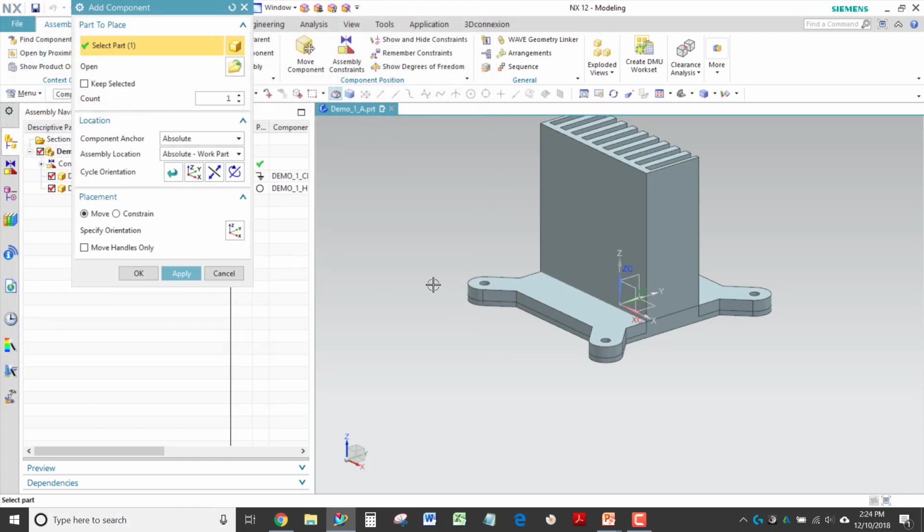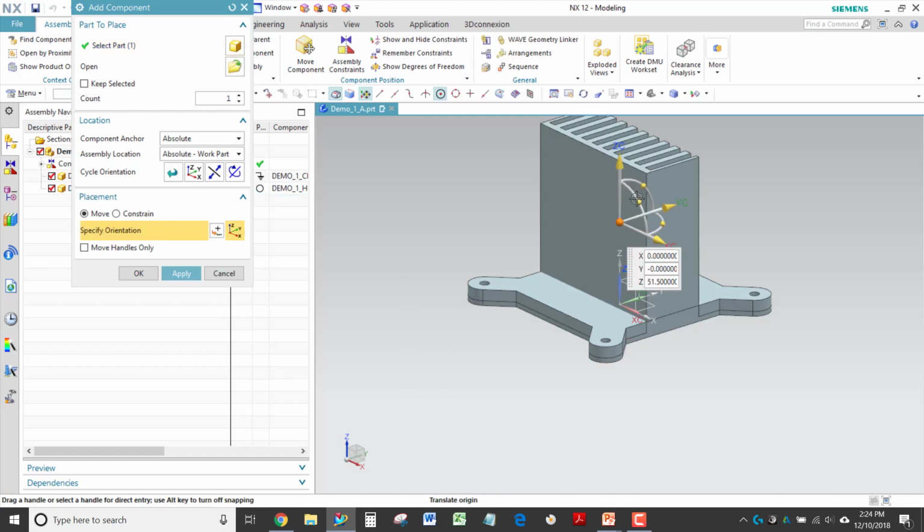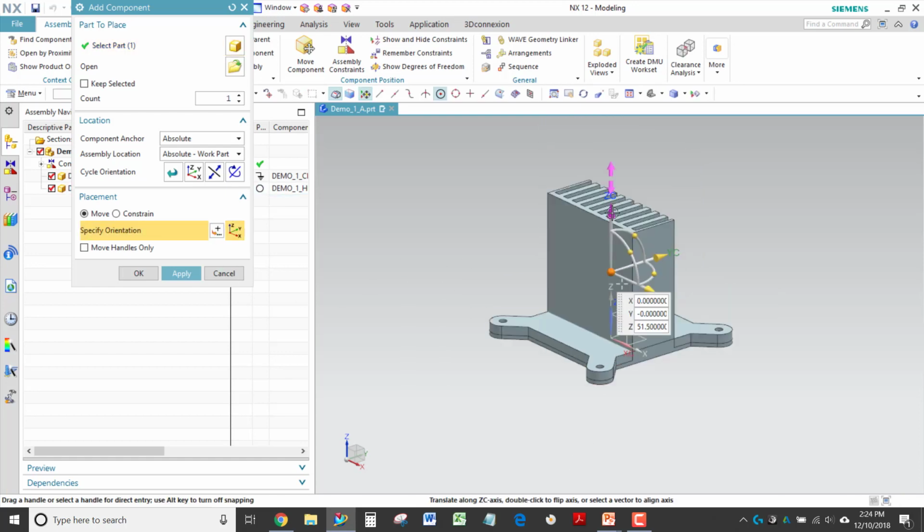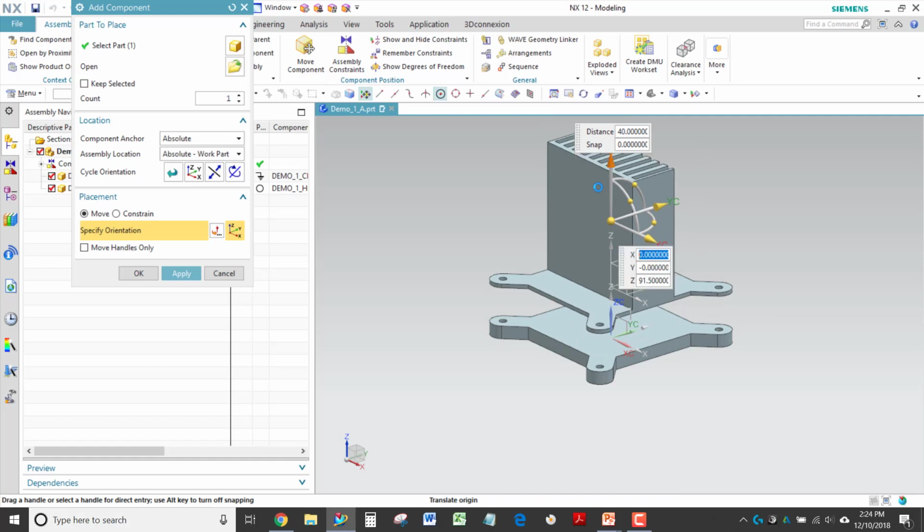So I'm going to open that, and here you can see it's overlapping our other component in an unsatisfactory way. So we're going to constrain this component. First, I'm going to move this component off the face of my block to give me some more room to see what's going to happen for my constraints here. So now we can do one of two things.